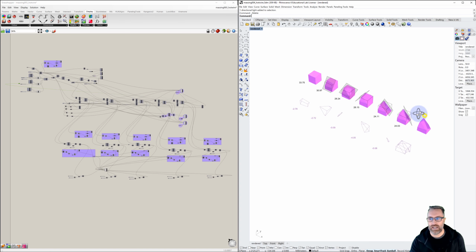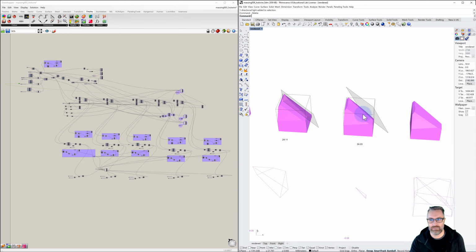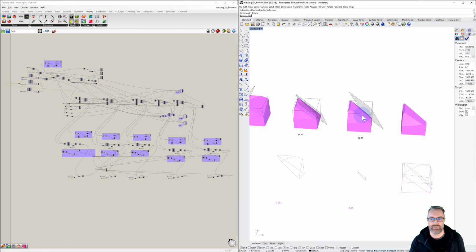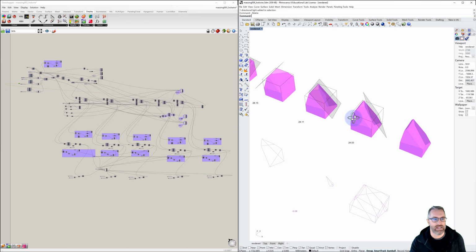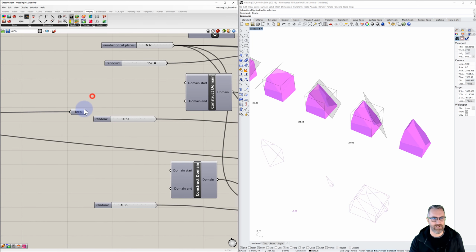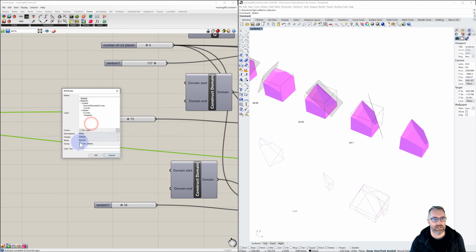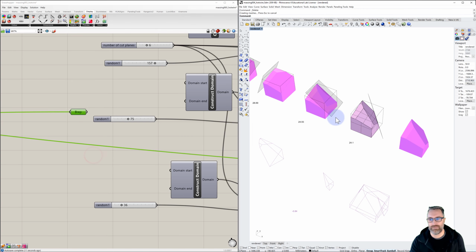So I've got at the end of my process here, a finished piece. And in my Grasshopper definition, I pulled a Brep container all the way over to the end so that as I make changes and as I see what this looks like, I can output, or I can bake, that geometry, and I'll pull it to the side, and I'll do one more.